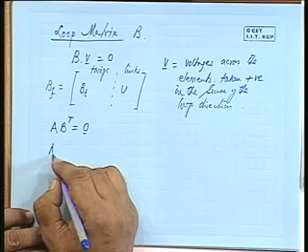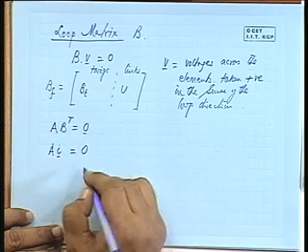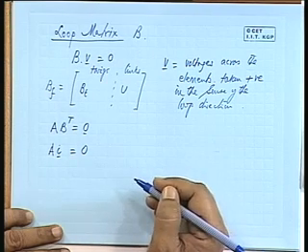A consists of the elements connected between nodes, and we take a plus sign for the currents of elements going out from the node, and those entering the node are given a minus sign. All right. So, you will find A into I is equal to 0.